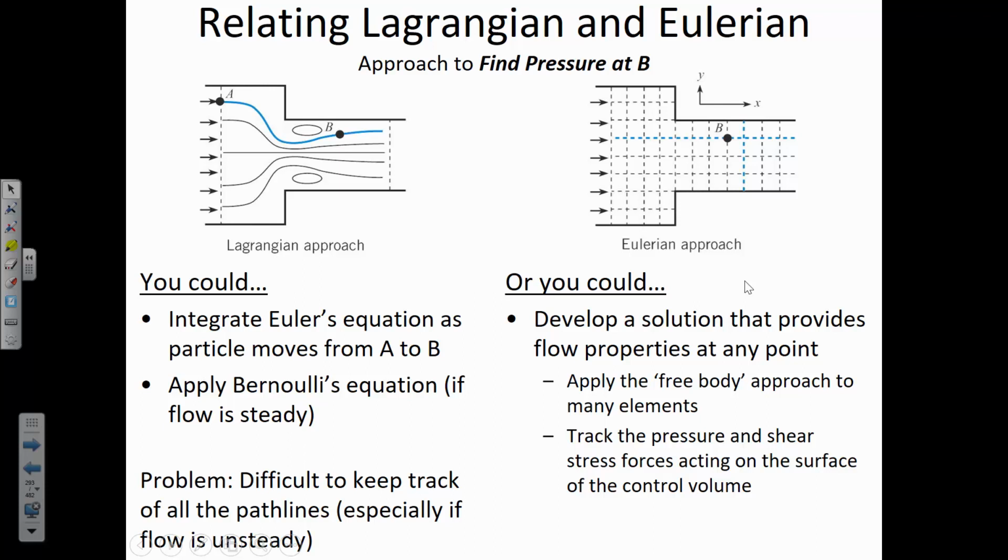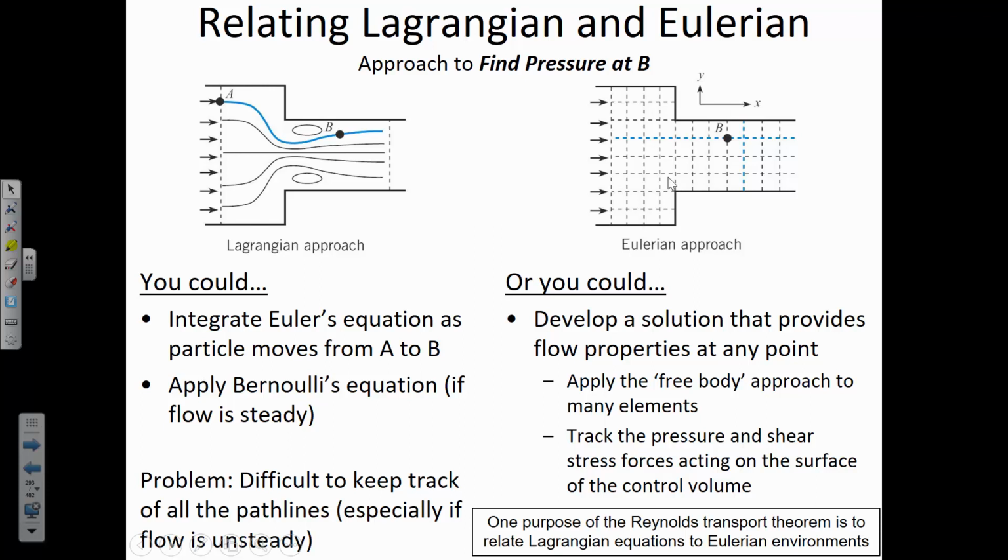And the other thing that simplifies this computationally is that the trajectory of the individual particles in the Lagrangian approach was unpredictable. You know, they're moving in a random direction sometimes, and there can be these vortices and eddies that complicate the flow patterns, whereas the Eulerian approach allows us to say, here is our control volume, the control surfaces are fixed, and so it takes some of the uncertainty out of doing the calculations. We can, in other words, apply the types of equations that are limited to Lagrangian ideas.